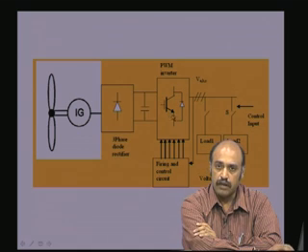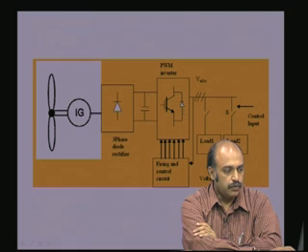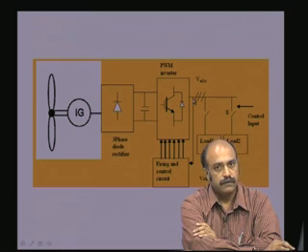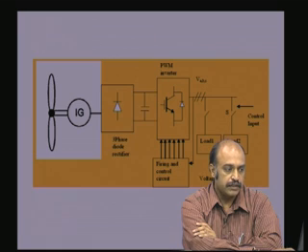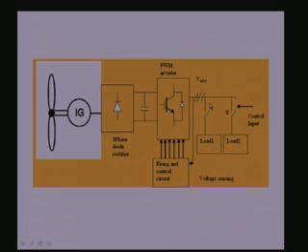These are the modulation signals, firing angle. These are IGBT or MOSFET bridges. So, by pulse width modulation, you can get out here 3-phase or single phase sinusoidal output voltage, which can interface with the load or which can also interface with the mains, the grid.